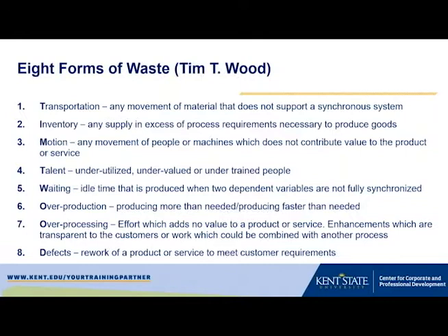Waiting is a big one. It's that idle time when either equipment is sitting idle or people are waiting, and that happens quite often in processes that aren't balanced well, or in batch manufacturing type processes, or in places where things aren't synchronized well. And again, doing lean activities here, putting in the right kinds of countermeasures can help to reduce waiting and other forms of waste. The last three, overproduction.